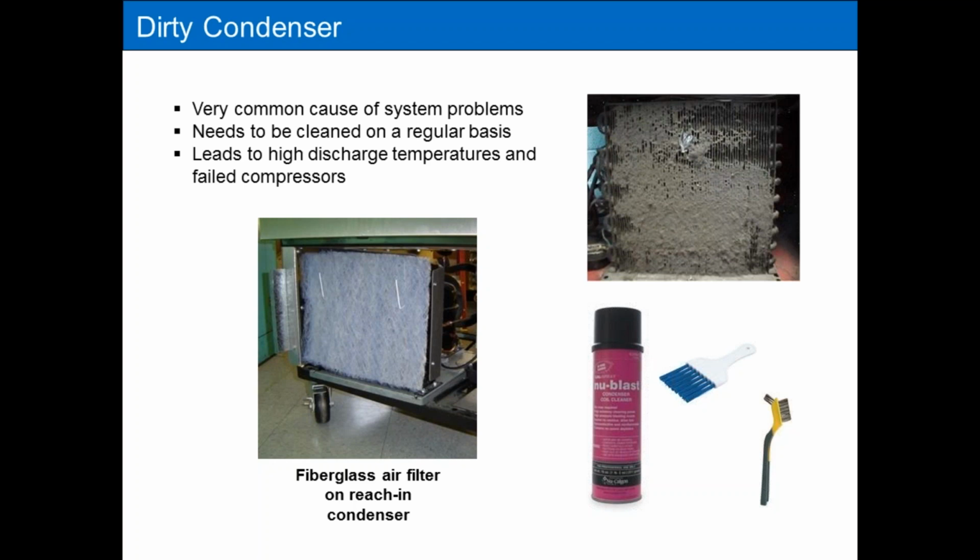But the problem you're going to have is that it's going to kick up a dust storm. If you're in a kitchen and you blow these out with compressed air or nitrogen or something, that dust cloud will go all over the kitchen. You're going to make some chefs, some cooks, very mad, because now they're going to have to clean all those surfaces off. And believe you me, I've done it. I've made some, not enemies, but some people very mad at me because I cleaned the condenser really well. I fixed the problem, but I made a dust storm in that area of the kitchen.